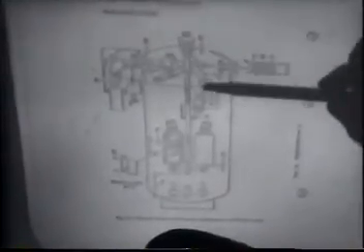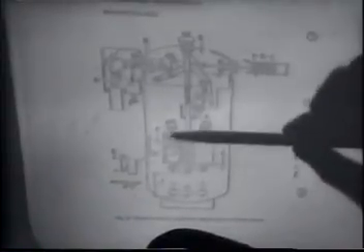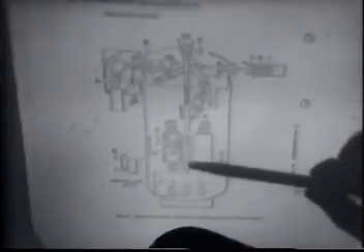And in this particular 69 kV breaker here, as you can see, right at the end of the breaker mechanism, we'll point this out, you have a compressed spring here that basically moves this amount D. As I recall, some 6 to 7 inches, depending on the type of breaker. This is a mechanical linkage here that moves these contacts from the closed position shown here to the open position here. And in a 69 kV breaker, this is in the order of 12 inches.